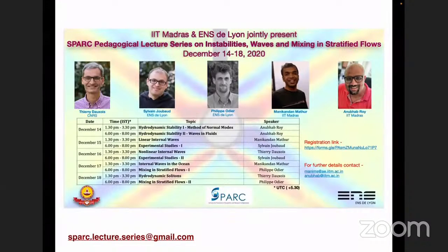So ideally, to do it in an exact manner, you should take the velocity profile for a turbulent boundary layer over a free surface. But the origin of the instability doesn't really care about the exact profile. Obviously, the growth rates that you compute would have some differences based on the exactness of the profile. But the fact that there is an instability, which is different from the Kelvin-Helmholtz instability, requires a shear profile, which means it requires a curvature in the flow profile. It cannot be a linear profile. It needs to be a profile that has some second derivative. That's what Miles said.